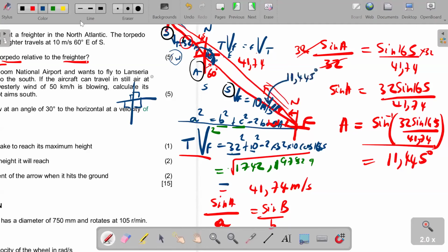So, before we calculated this angle, this whole angle here, I will try to increase this so that it's quite visible. This angle, how do we know it? Remember, this line and this line are north lines, and all north lines are parallel to each other. Meaning, if this angle here is 60 degrees, so is this angle that I have marked in green. It's also 60 degrees. Why? Because these are alternate angles.